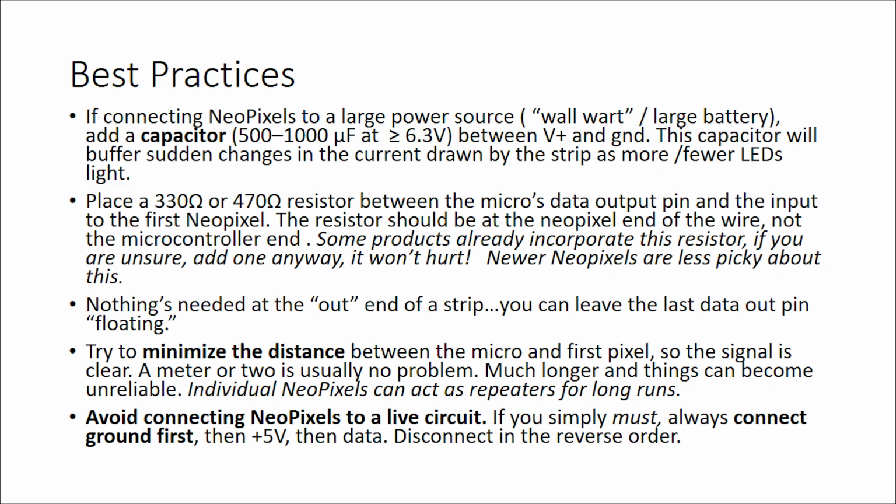Preferably put your resistor at the NeoPixel end of that connection. But again, if you're buying modern tapes or boards from China or from Adafruit or any of these people, there'll already be SMD components to do this work. But be aware of it, that if you're having trouble, this is the stuff you're checking, essentially.